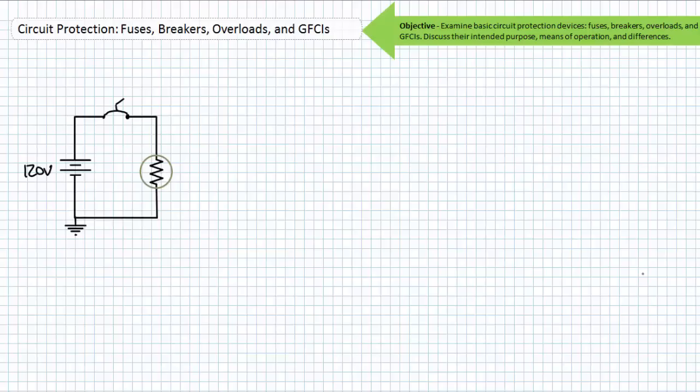Consider an electrical device enclosed in a conductive frame. This could be a washing machine, a kitchen appliance, a motor, or anything electrical meant to interact with humans. The innards contain the electrically active components and conductors, yet the frame and buttons servicing the machine should be electrically neutral and safe to touch. The negative terminal of the voltage source supplying this device is intentionally grounded, meaning the positive side is referenced from ground. This is one aspect of grounding known as system grounding, meaning the electrical connection of one of the current carrying conductors to ground, in this case, the one leading to the negative terminal.